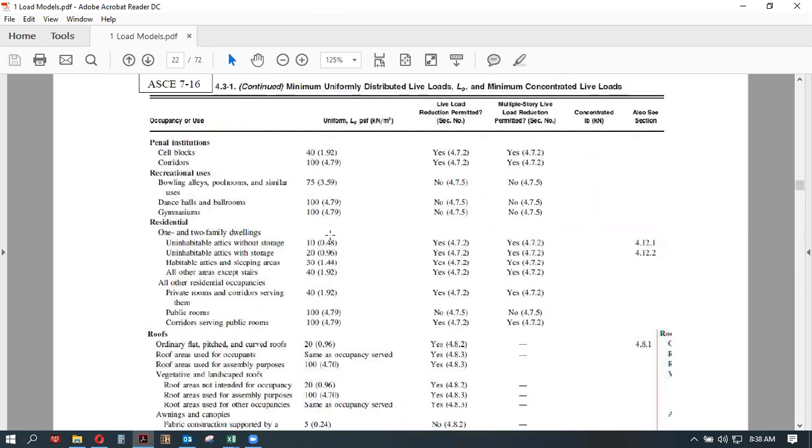What you would go do is you'd go in and look at some of these spaces that were renting out to law offices, law firms, and you would look to see in the floor system, did they do anything to accommodate the heavy loads that oftentimes are in law offices. They have these movable stacks of all these documents, and those get up to around 150, sometimes even 200 pounds per square foot for a live load. And you want to make sure that that floor system has been designed to handle it, because your typical office space would be 50 pounds per square foot.